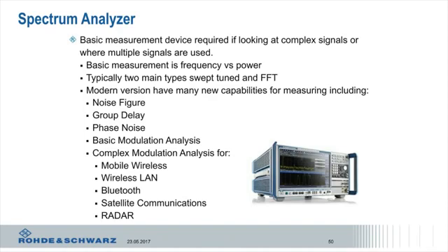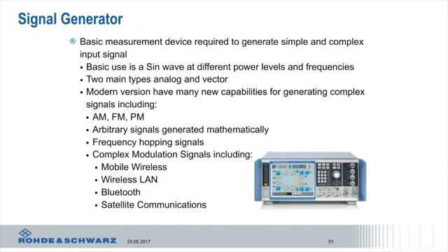Spectrum analyzer, this is again more in my world. So I'm looking at frequency versus amplitude, but I can measure other things, group delay, phase noise, noise figure, complex modulated signals like things in cell phones or wireless LAN. We have the ability to process some of those signals. Okay, another thing, signal generator, it really acts like a transmitter. It generates all of these signals and then some and gives you the ability to emulate, if you're receiving something, transmitting to you in some format that's predefined and predictable.